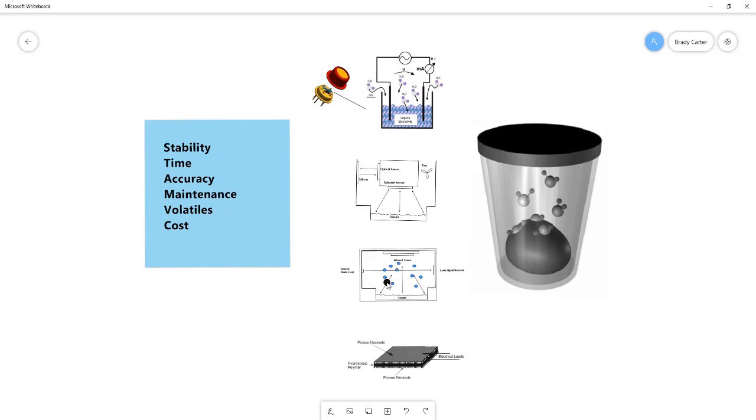As well, the tunable diode laser is actually susceptible to pressure changes. So any elevation changes will impact its readings, and in fact, each reading needs to be adjusted based on the pressure. So that means that the two electric property sensors tend to be more stable in that they aren't as affected by the user and potential contamination.